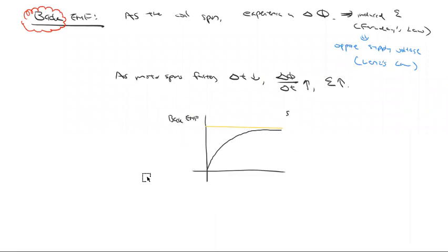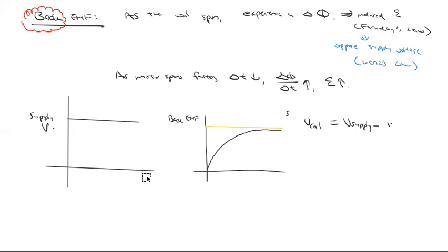So you've got your supply voltage on the left, which we're assuming is constant. Then you've got your voltage across the coil, which must equal supply voltage minus back EMF. That's why as it spins faster, it starts at the supply voltage and then gets closer and closer to zero. It depends if you're talking about real life or the ideal.